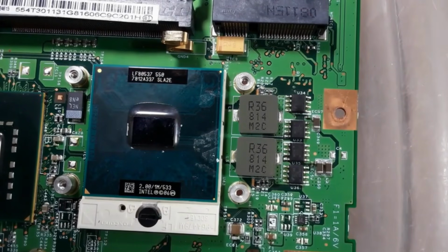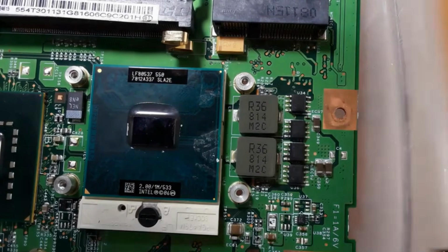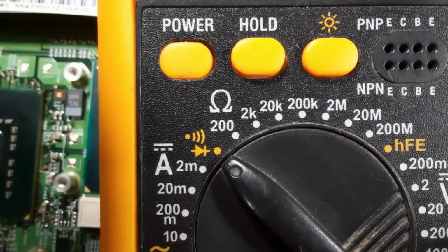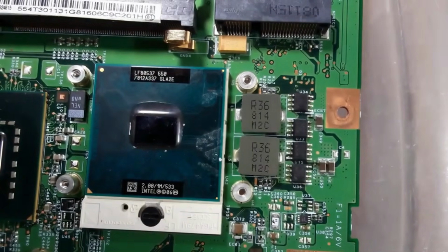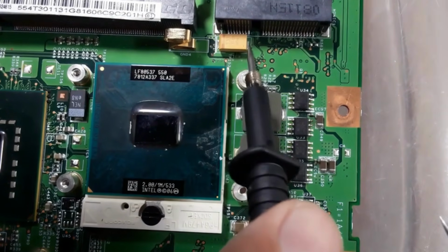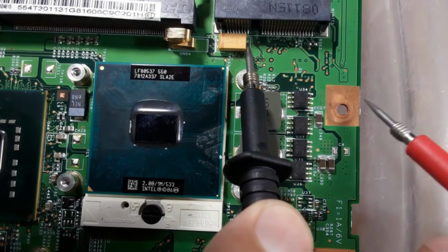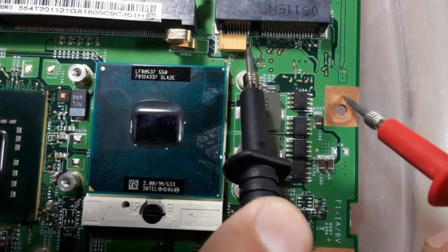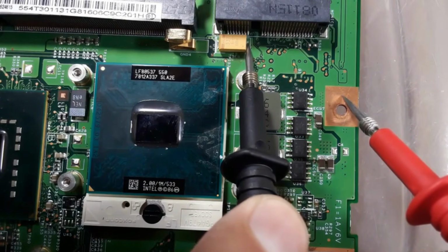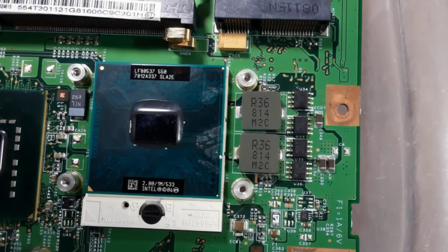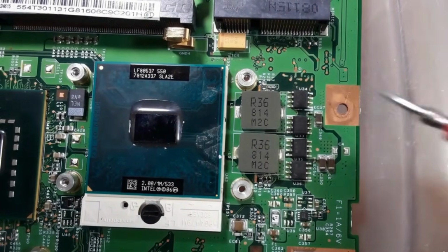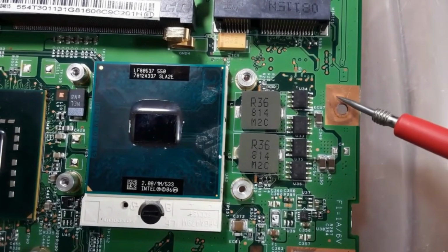Let's check using the multimeter. So we should just put the multimeter on the buzzer option, as you can see, and let's check. So let's put one probe here on this capacitor, as you can see, and put the other on the ground. Do you hear the buzzer? It means continuity. Okay? So this part is connected to this. Of course, as you can see here,